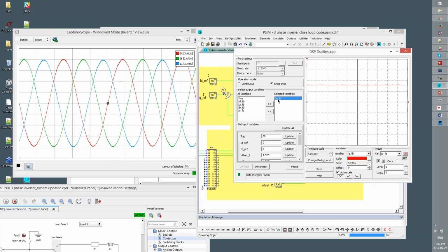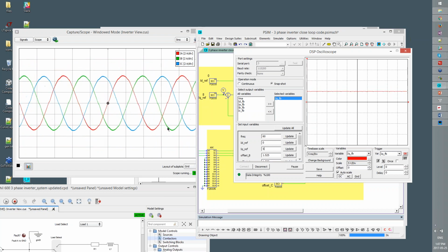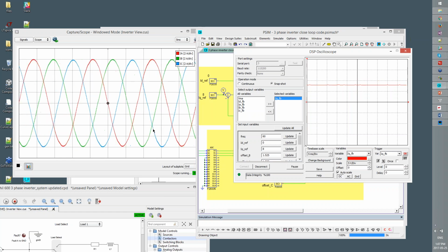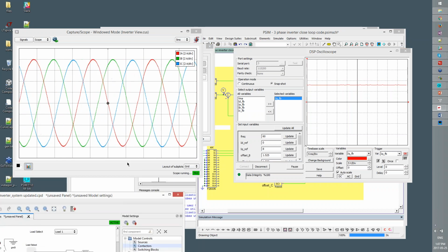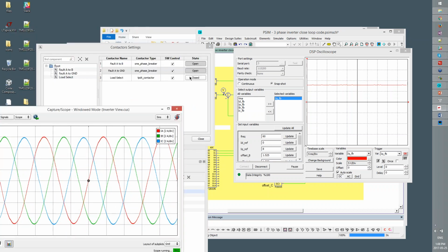So we've got IQ feedback right now. It's set at 8 here, and we can change this around. If we push it down to 5, we can see that we're getting good control. If we go really small, we start to get deformity in the control signals, and we can increase the current again. We can also see what happens if we toggle the load again.